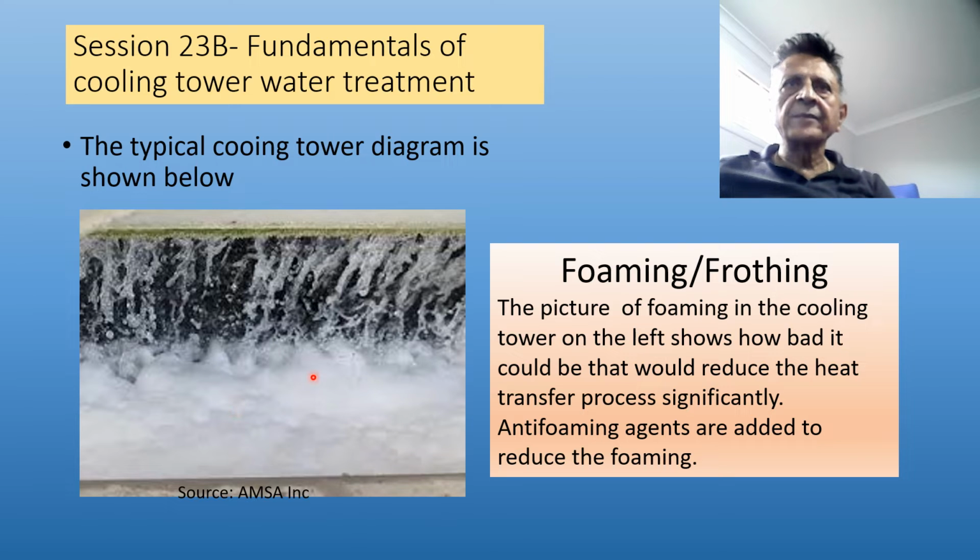You will notice that the amount of bubbles has created so much that there is hardly any water in the system. Therefore, with the absence of water, the cooling tower in the chillers, there is a reduction in transfer of heat from the compressor liquid to the water.